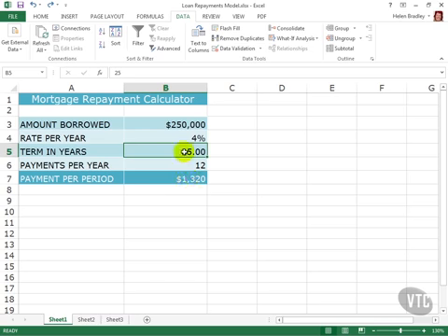This is what I call brute force calculation. You force values in here and check to see if you get the right result. And in fact, Excel GoalSeek is going to do exactly that for us. It's just that Excel is a whole lot faster at doing it than we are ourselves. Let's see how we'd use Excel GoalSeek to solve this problem.